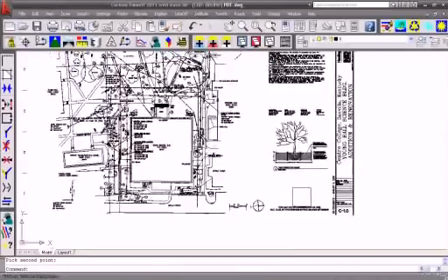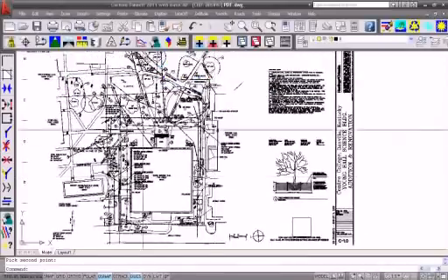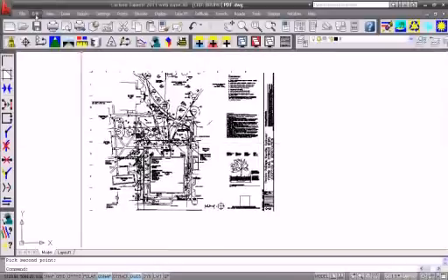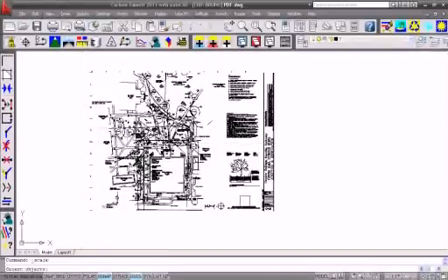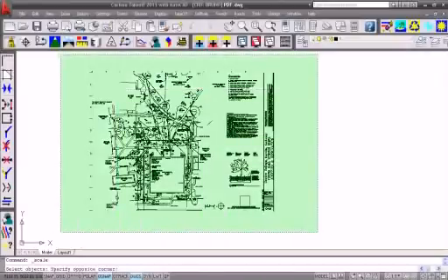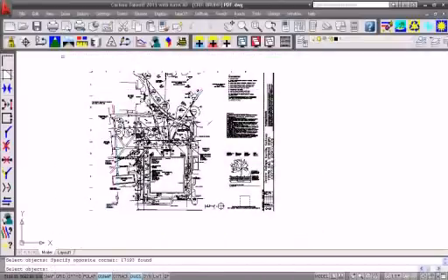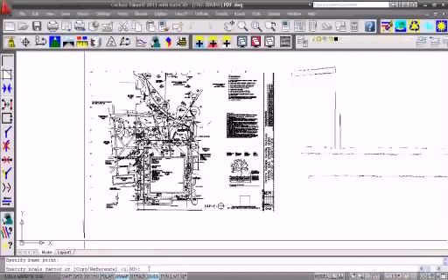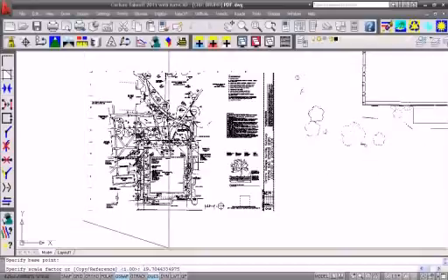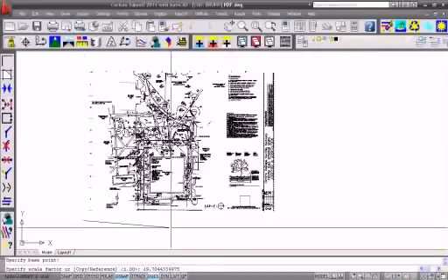The 2D scale can take a long time on a drawing this complicated to convert it. So I'm just going to use the AutoCAD scale and use that factor. Okay, select object, base point, and paste in that value. Okay, and hit enter.